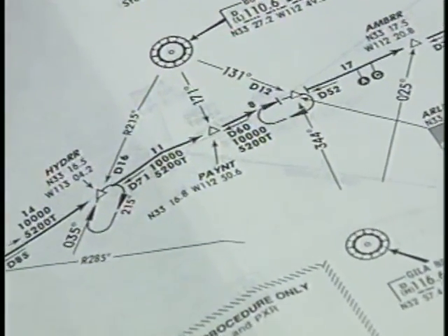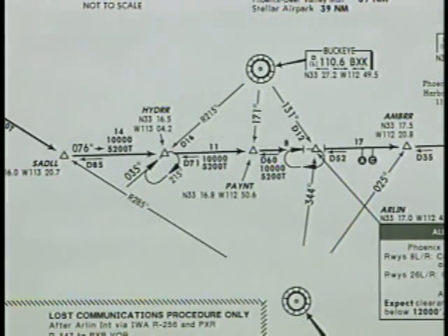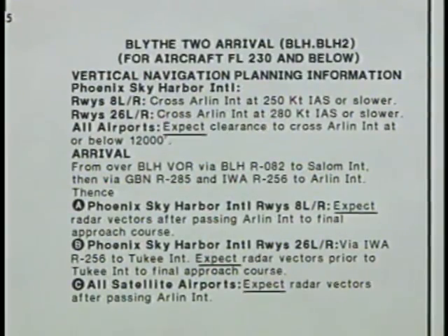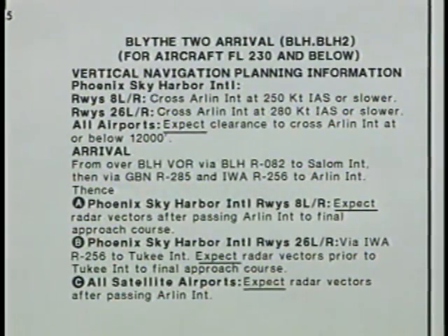ATC can assign you a STAR even though you have not requested the procedure, unless you have indicated no STAR on your flight plan. If you accept the clearance, you must have the charted procedure or at least an approved textual description of the STAR.